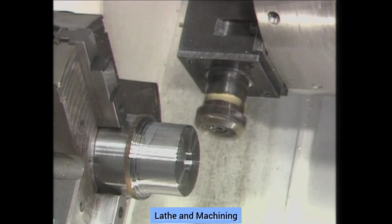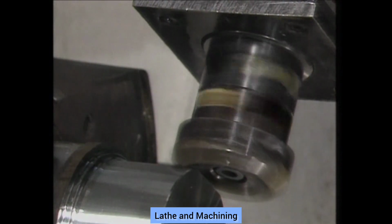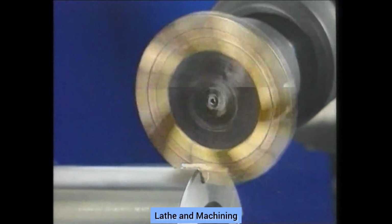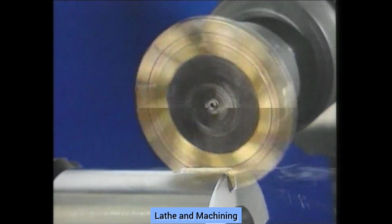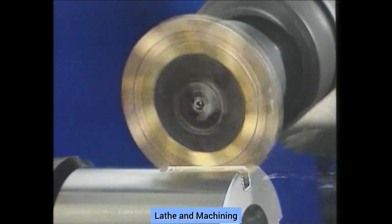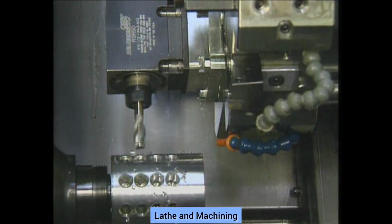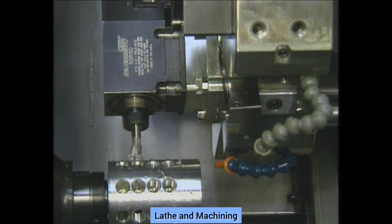Turn mill NC turning machines add milling operations to the machine's capability. For milling operations, the workpiece is held fixed or else rotated at a very slow speed while rotating tools, sometimes called live tools, are brought to it. The main benefit of the turn mill lathe is that more complex workpieces can be finished on the lathe and not have to be moved to a second machine tool for additional operations.